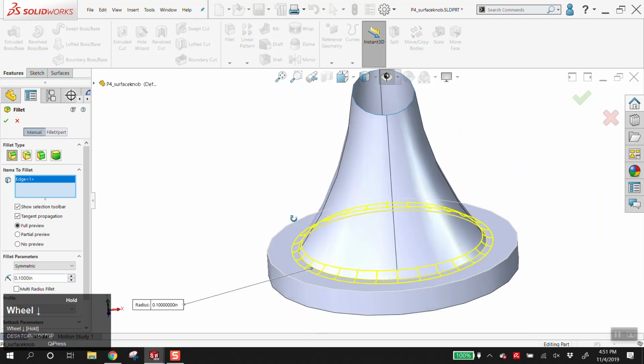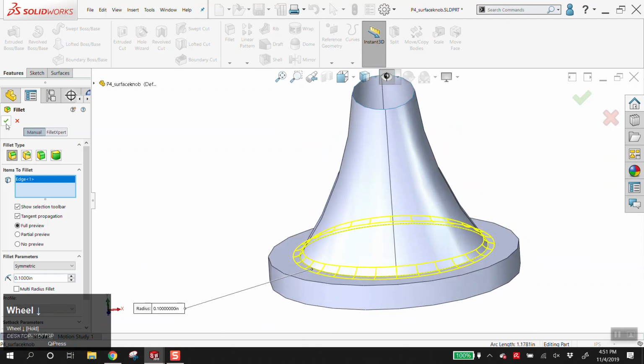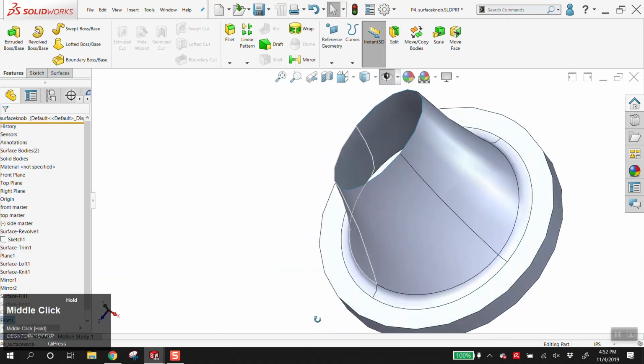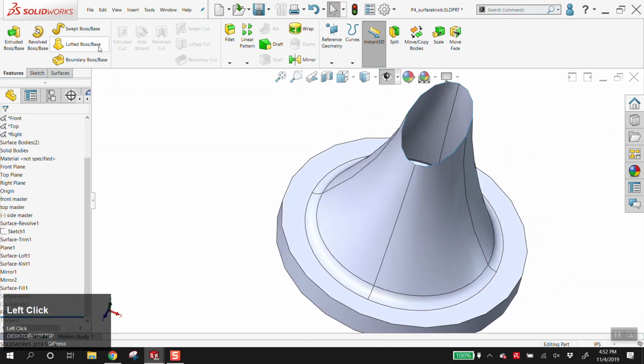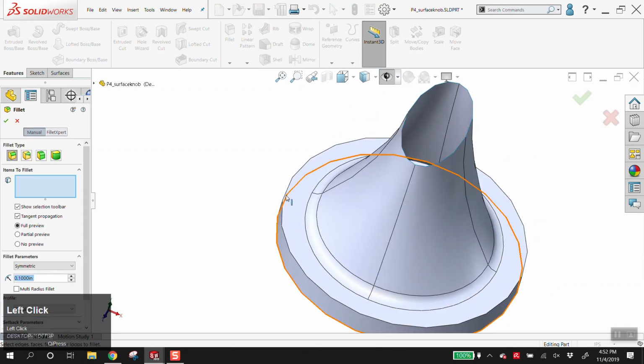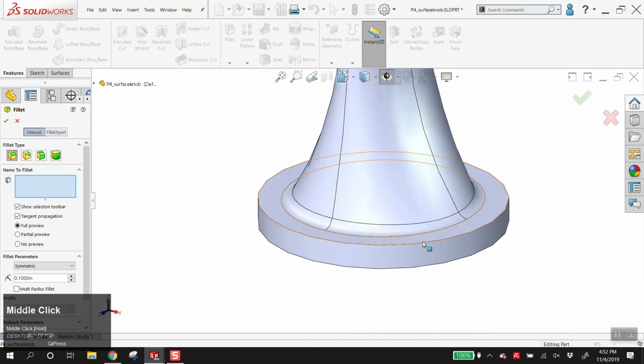And all it does is, on the inside, it's paper thin. So the fillet now also exists on the inside as on the outside. You cannot, however, fillet this edge because there's nothing to fillet to. It has to be a corner.